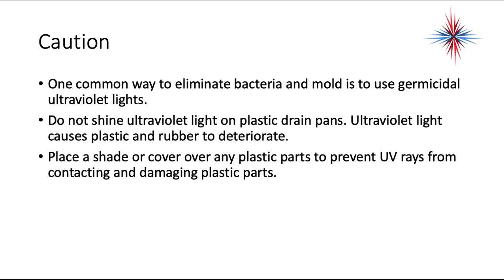A common way to eliminate bacteria and mold is to use germicidal ultraviolet lights. However, do not shine ultraviolet lights on plastic drain pans. Ultraviolet light causes plastic and rubber to deteriorate. It cannot be where there's a drain pan. Place a shade or cover over any plastic parts to prevent UV rays from contacting and damaging plastic parts.